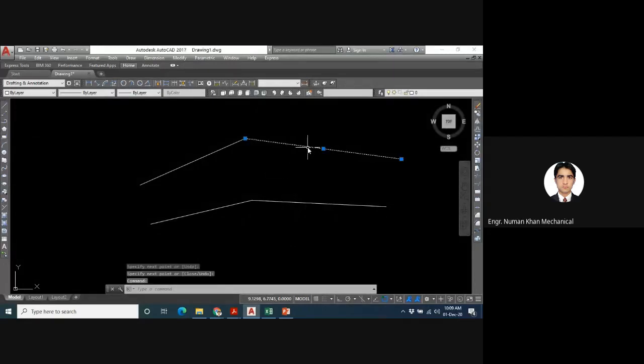If I click on the line, the object that I have drawn with the line segment consists of two different entities. Entity 1, entity 2. I can select them separately. But if you look at the object that I have drawn with the polyline, it is a single entity. This is the main difference between line and polyline. And we use polyline when we draw objects and want to convert those objects into 3D solid objects. So it helps us to have a closed region. You can see there is a bond between these 2 points. There is not only a common point, there is a bond between these 2 points, but there is no bond between these 2 points. You can see very clearly.